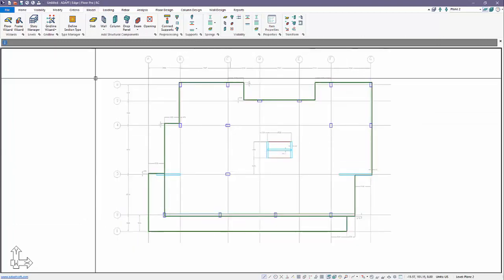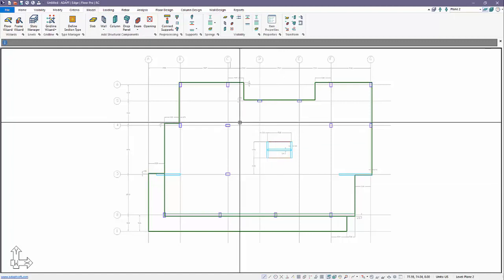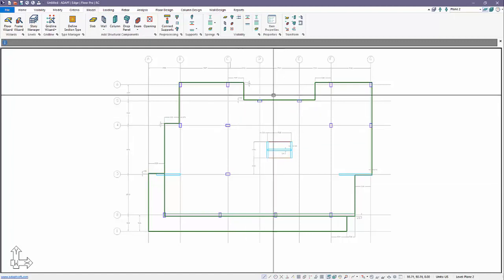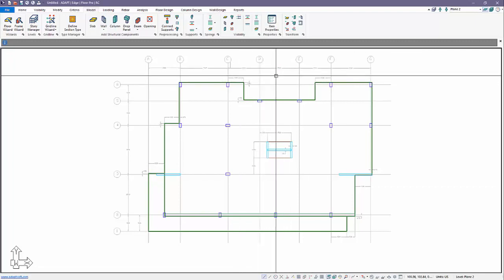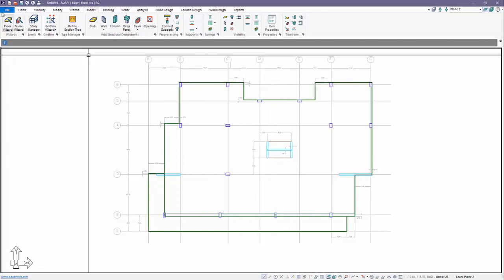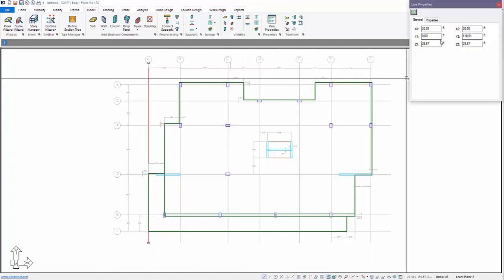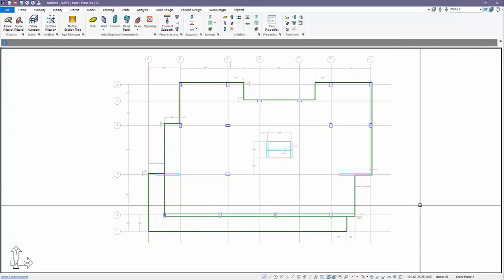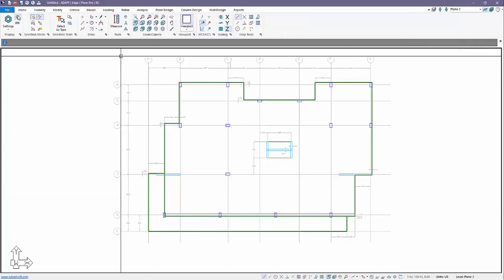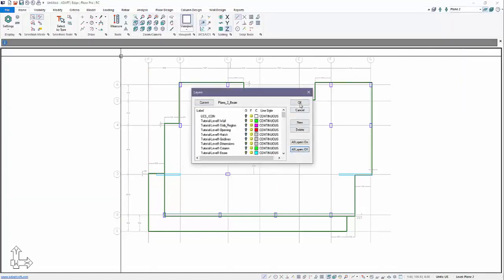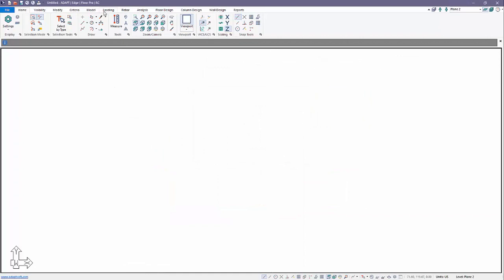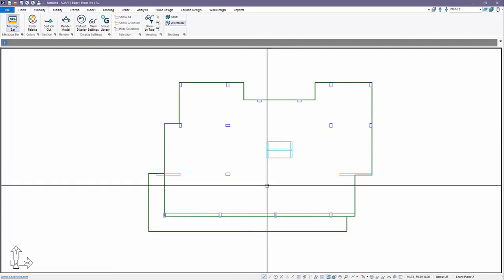I'll turn my CAD file off. I may not want all of those lines. If we want a separate grid file, we would have to import that separately. This particular grid file can be left on only through filtering layer. So you could technically leave this layer on, turn everything off, leave this grid layer on using the grid lines layer. We'll turn everything off again, and then I'll just reset my structural view from visibility. We'll go back to the default display.